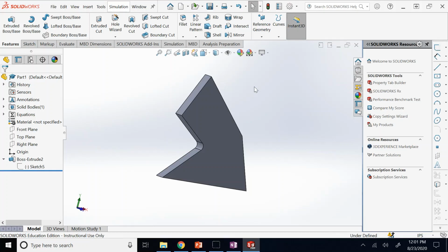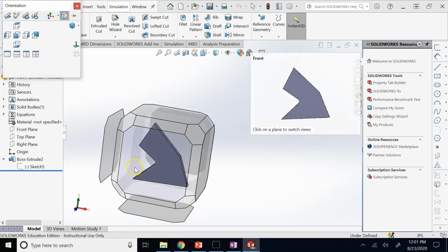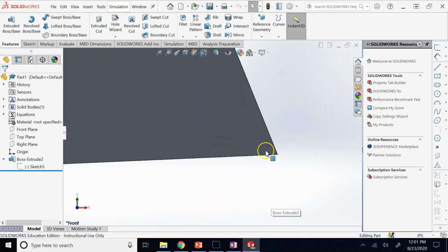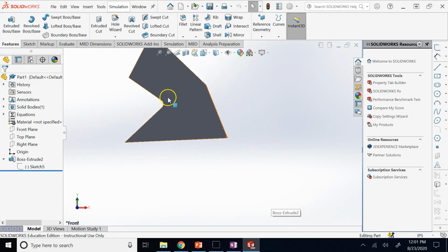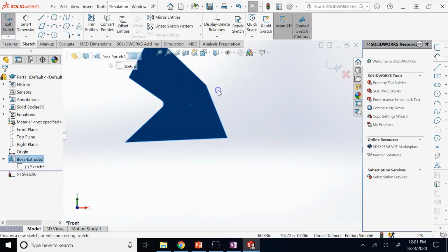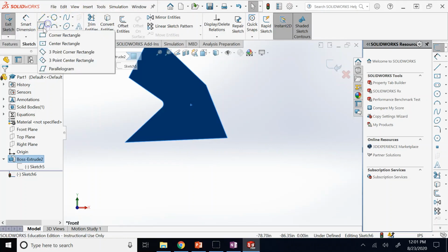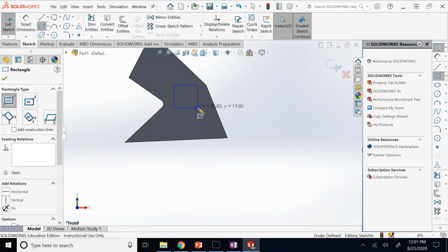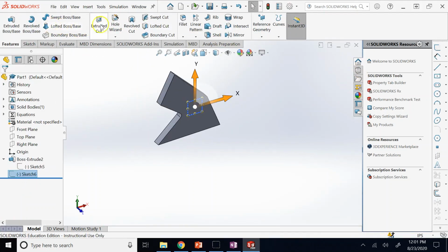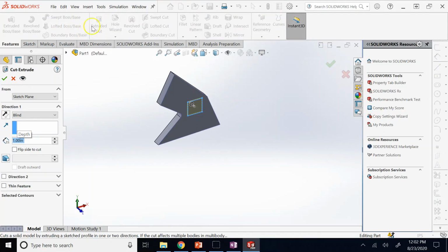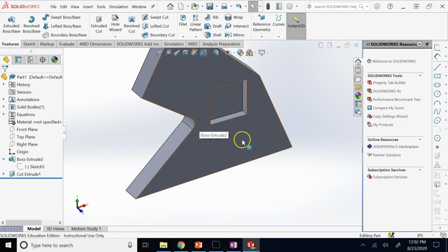And the other thing is, if your part is to be made by CNC machines, CNC machines always have a radius of a tool. And so when you want to go around and create the part, you cannot really create super sharp corners like this with a CNC machine, okay? So for example, if I do a cut on this so that you can visualize what I say a little better. So let's say you have a part and then you want to cut something like this out of it. Right, you have a pocket like that.